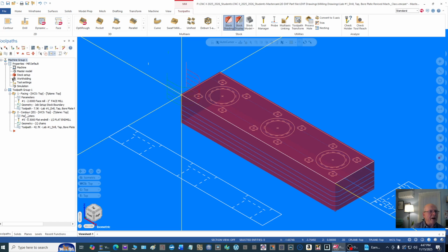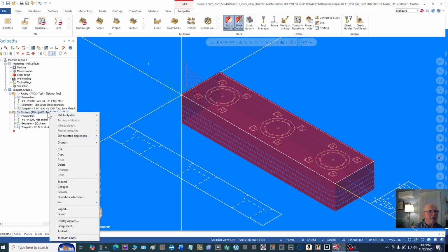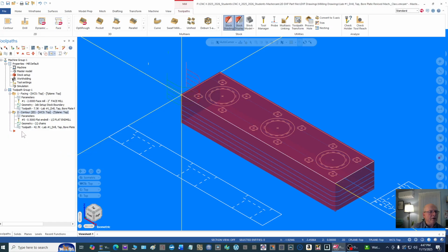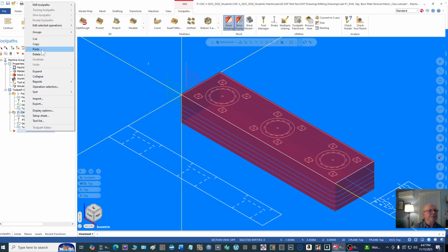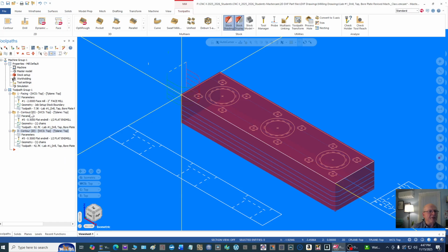We can go up here and grab the contour here, and right click and say copy, and then come down here, left click on that, just to momentarily, as you see what I did, I got a shade there that tells you that you're picking that spot. Right click and say paste. So what I actually did is I copied this and put it down here directly below it.